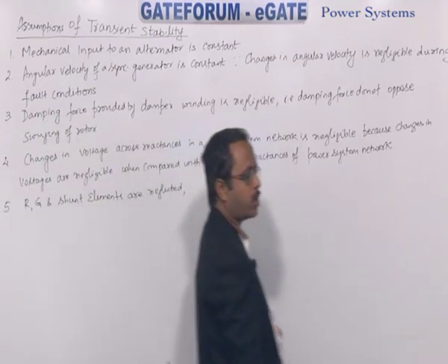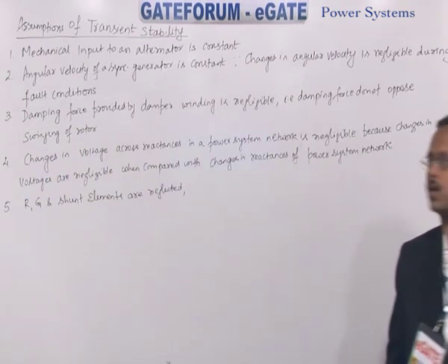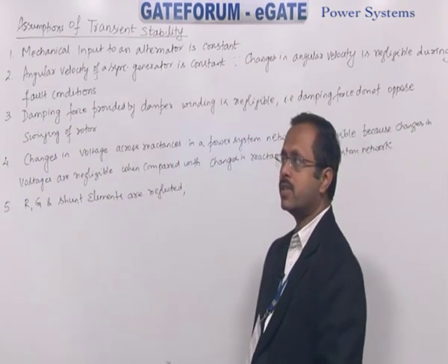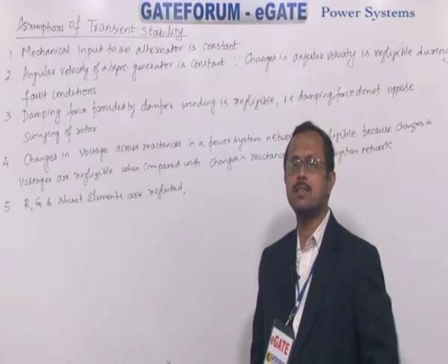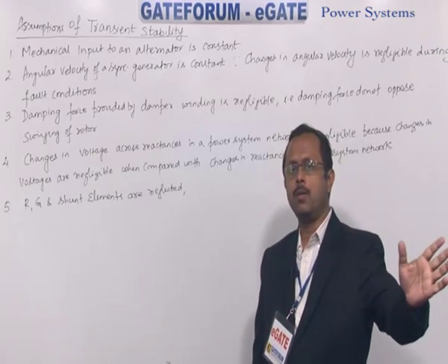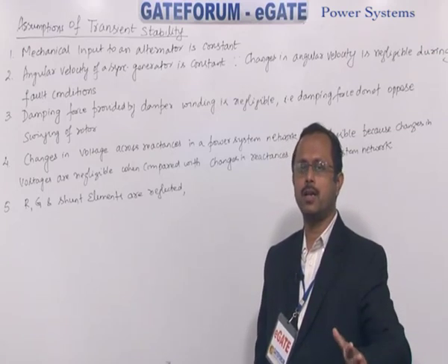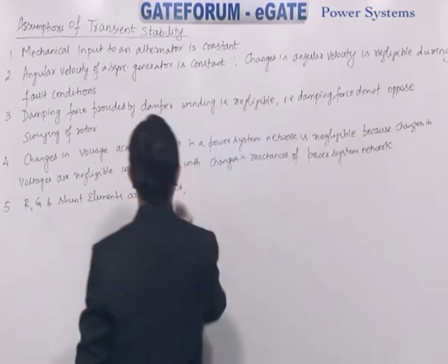And in such a case, what is the next step? You determine, or you say model, the remaining network with a transfer reactance. What do you mean by transfer reactance? The reactance between the source and the load by eliminating the fault point, you define as transfer reactance.